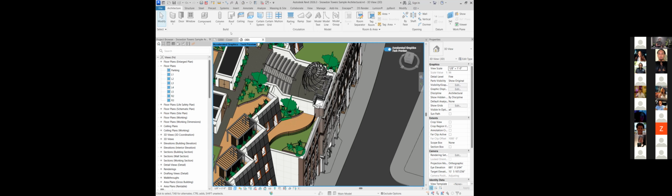So that's another point that I'm glad you brought up. There are some things that don't fall in any category. It's not as simple as furniture, where you just add it to the furniture category. But in the last presentation about schedules, remember a schedule will categorize objects in Revit according to the category they're in. So there may be a case where I ask you, Mateo, to build a gate, but I don't want you to categorize it as a railing because I want that gate to show up in my door schedule. You get where I'm going with this?